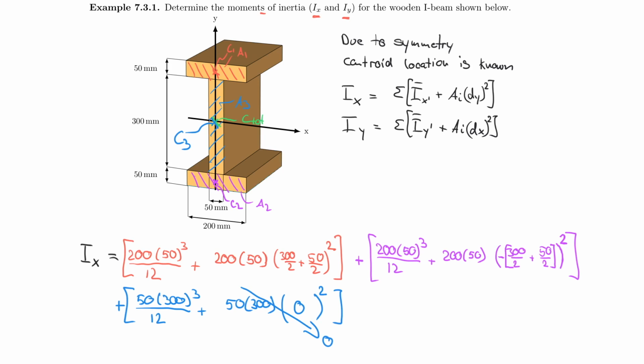And notice that here I use the summation, right? So remember what I said earlier, that if you just sum up this part and this part and this part, you would not get your final answer, because you're completely ignoring this part, which is the parallel axis theorem part, and here as well, which actually adds a lot of stiffness.